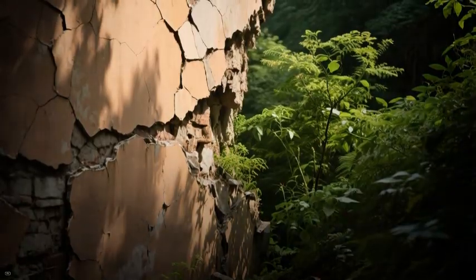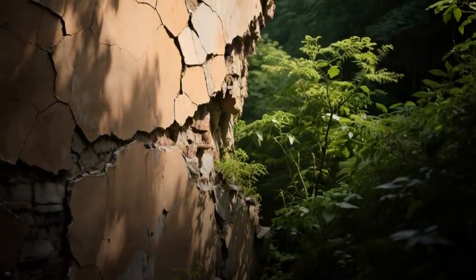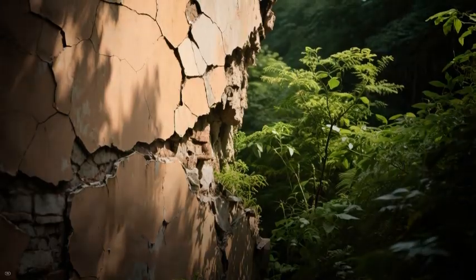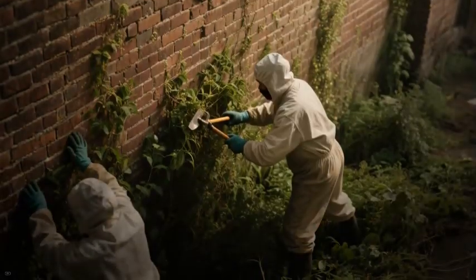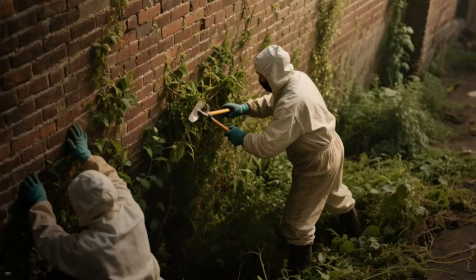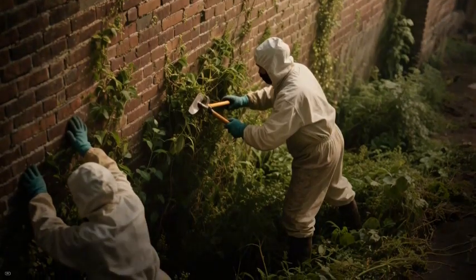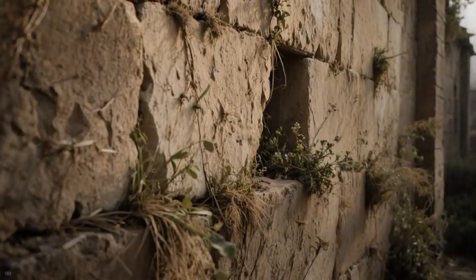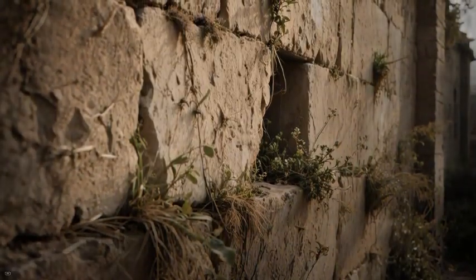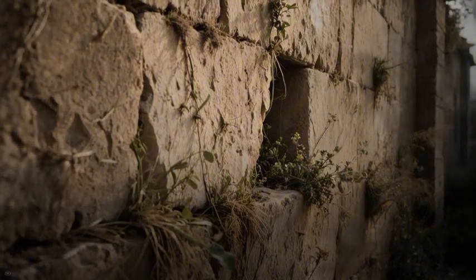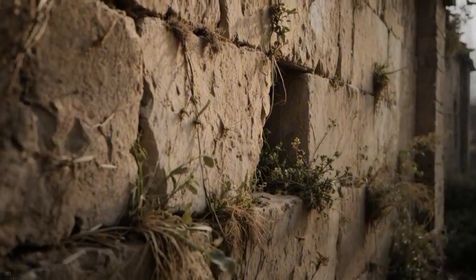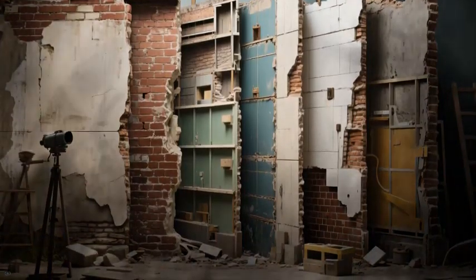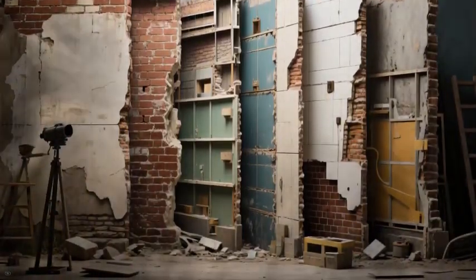Vegetation management was another part of maintenance. Plants growing on or near the wall could cause damage by breaking apart the soil or shifting stones. Workers cut back grasses, shrubs, and tree roots, ensuring that growth did not interfere with the structure. In some regions, particularly where soil was loose, vegetation was allowed to remain in controlled areas because plant roots helped stabilize the surface. These decisions varied according to local conditions and reflected practical knowledge accumulated over generations.